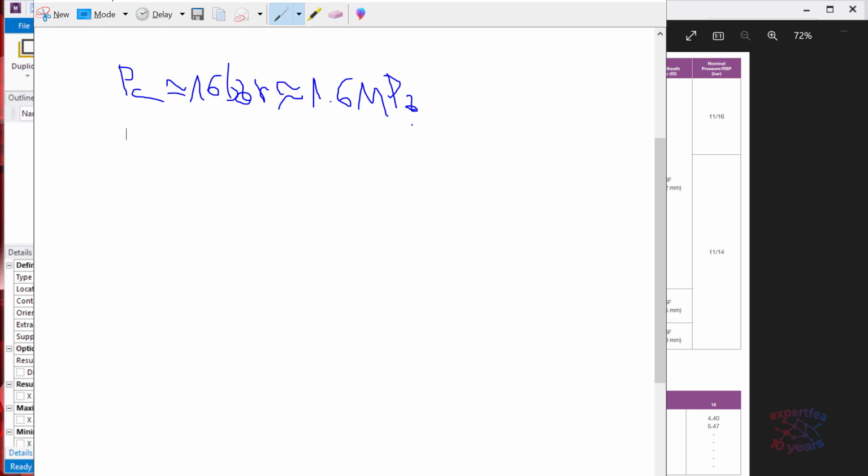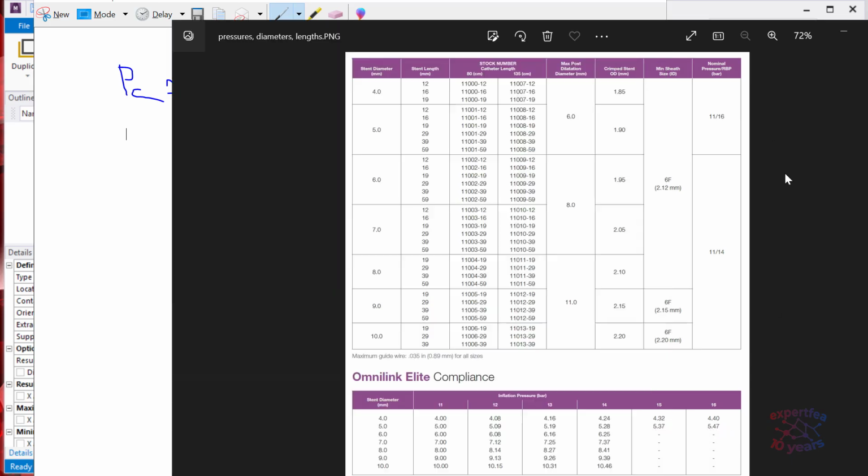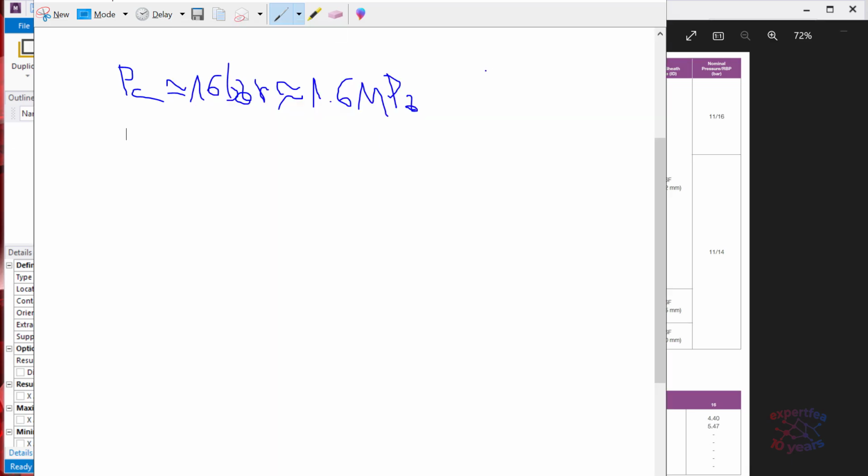And in order to make a correct correlation, let's change the displacement. Instead of 0.35, let's make it 0.23 as prescribed here. So this should mean that it is applied to, let's say, radial displacement 0.23, instead of what we have now, 0.35 millimeter, yeah.